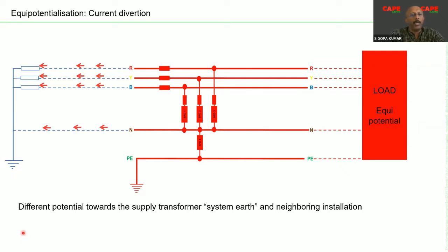It goes to the source, and a part of this current probably goes through the neutral earthing and so on. It also gets dissipated as heat in the conductor. So this is basically how an SPD operates. At your origin of installation, you need an SPD, and most often the incoming equipment are protected under several conditions we need to fulfill. Mostly, fulfilling these conditions is quite difficult.